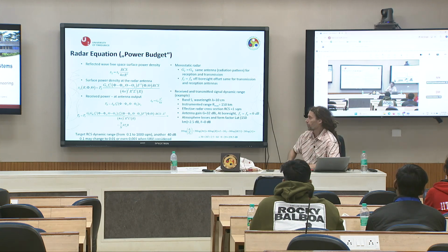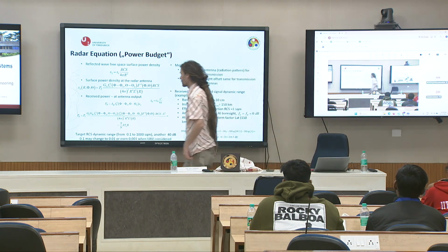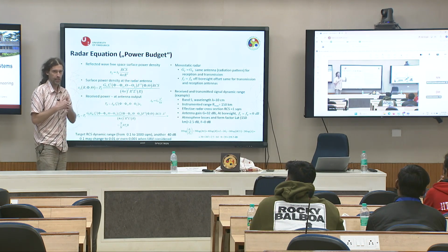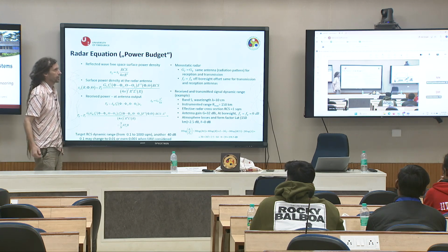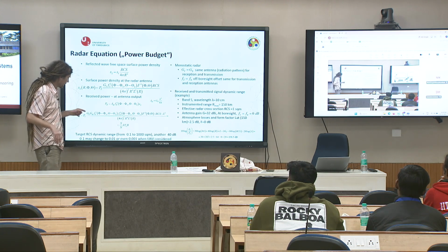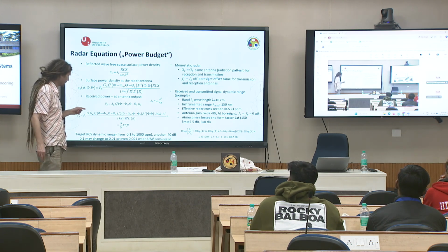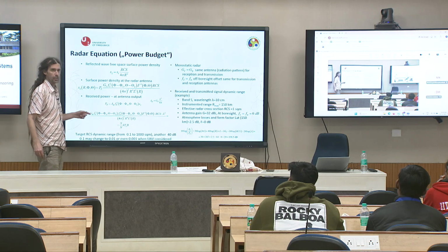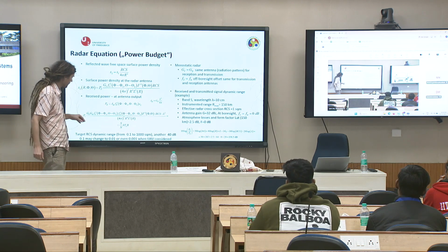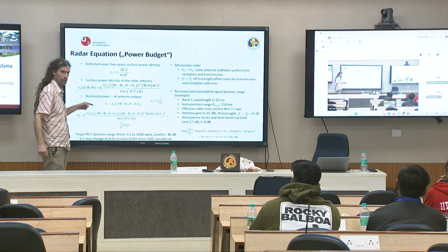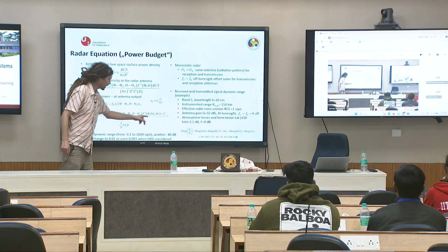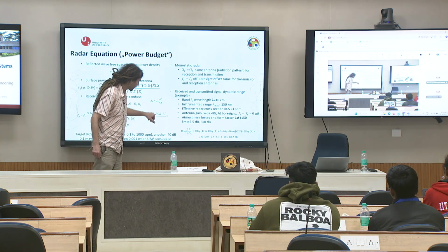So generally what is important for us is the transmitted power. Okay, it is a clear message. Like the transmitted power in the previous example was 14 kilowatts pulse. Then the transmitter antenna gain, maybe 30, 34, 40 decibels, something like this. If we use the same antenna, it is the same numbers, of course. This is the antenna part. I will skip it because we don't have time.